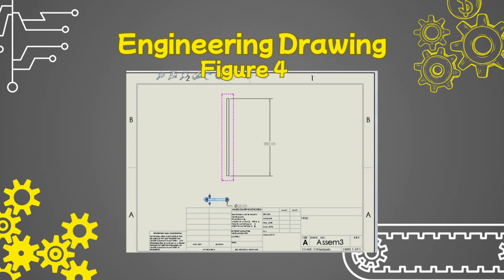Based on the simulation reports, the results were excellent and showed the design is safe. First, stress. The results showed that the maximum stress ranged between only 2.16 megapascals and 4.37 megapascals. These values are very small and safe compared to this material.